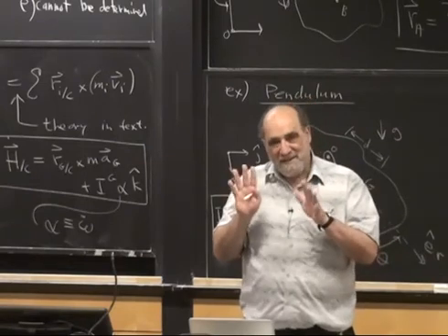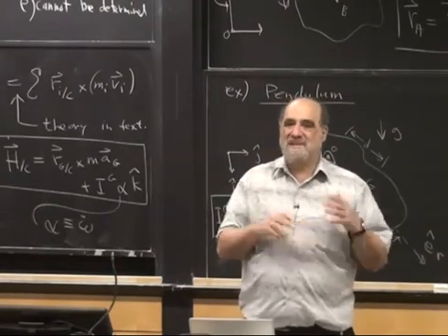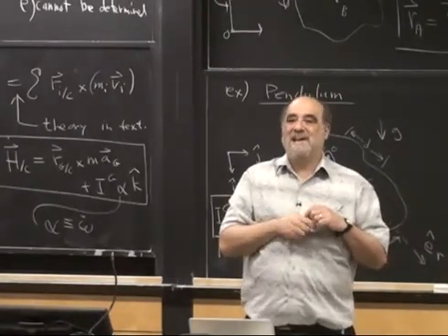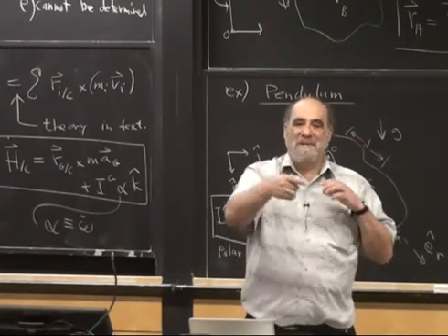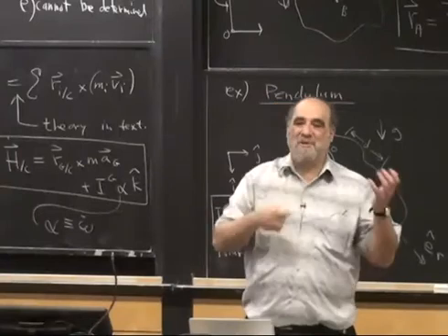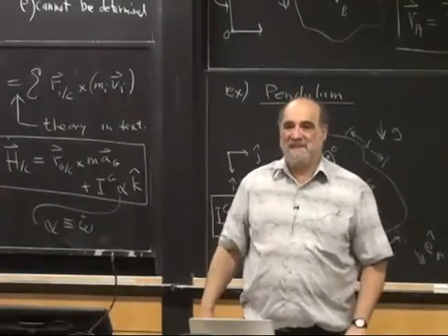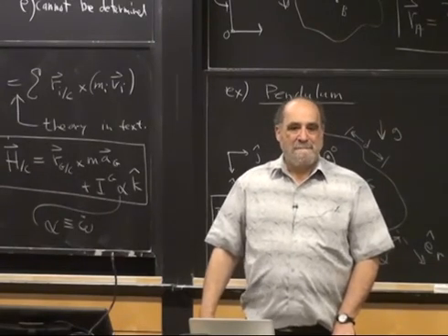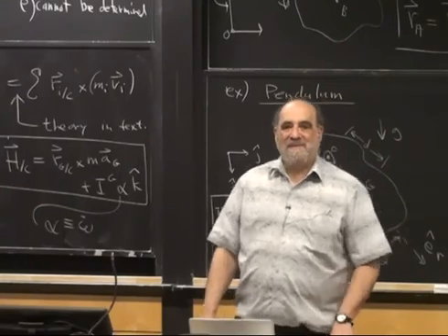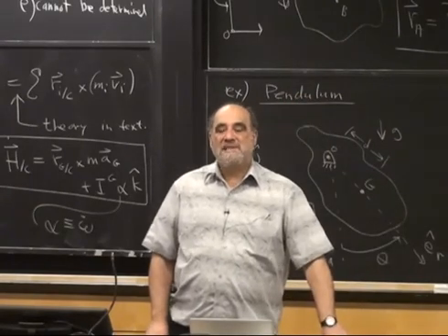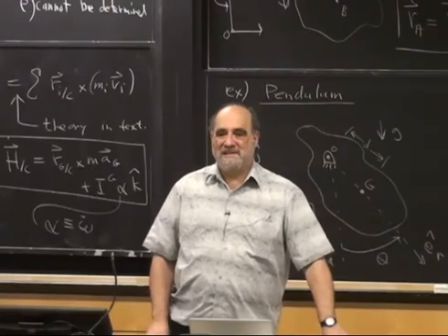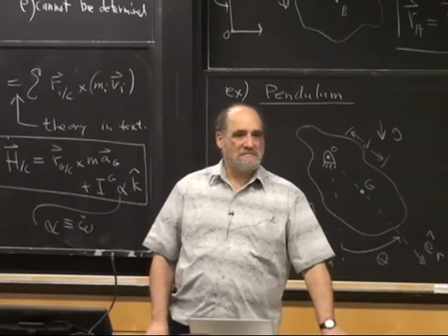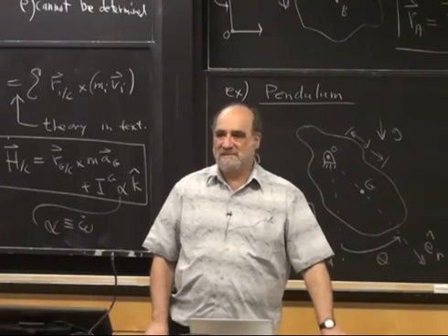So probably the answer to your question in terms of practical usage is in 2D problems, you think of it as moment about a point because you're not always drawing the line out of the page. In 3D problems, you're always using moment about lines. If you care about moment about 3 lines through a point, you call that moment about a point because the 3 components of that vector are moments about a point. Does that address your question? The fundamental concept is moment about a line, and if you go back to chapter 2, the whole cross product section is motivated by the concept of moment about a line. Okay, other questions?